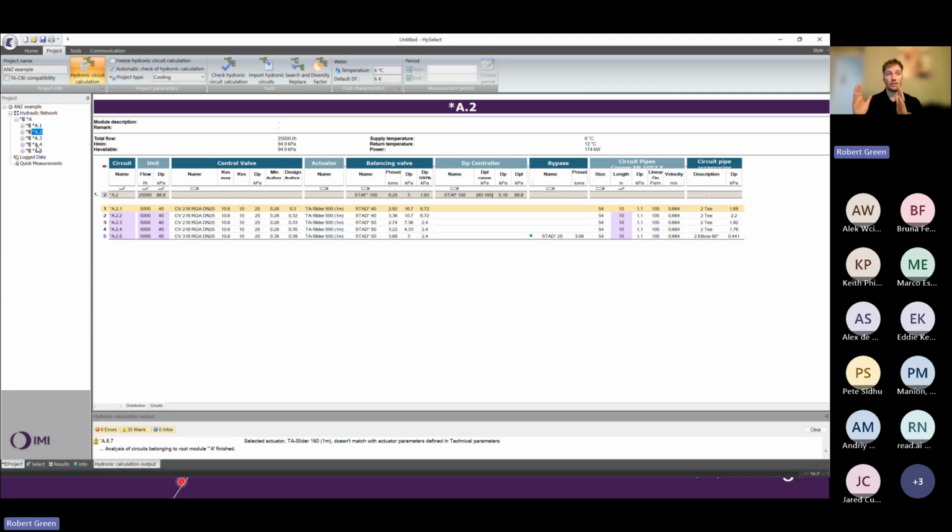And then what you would do is close a number of circuits, as in branches. So for example, if my pump has only been sized for, let's say, 50% diversity for the sake of argument, really big diversity, you would close, in this case, 2 of the branches, and prove that you can still get flow in the 3 that remain open.